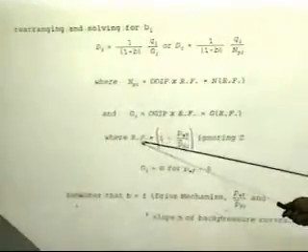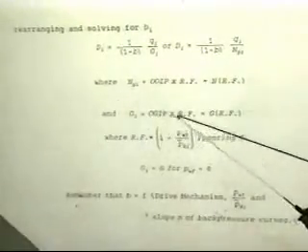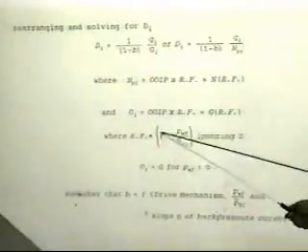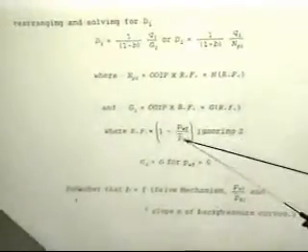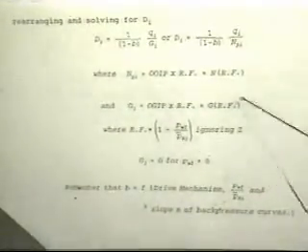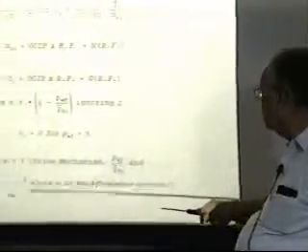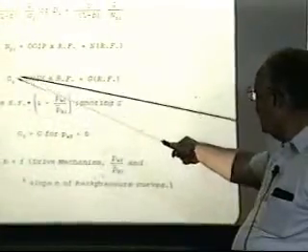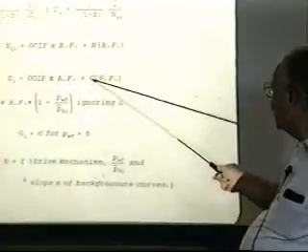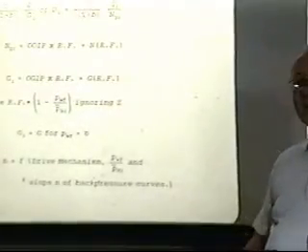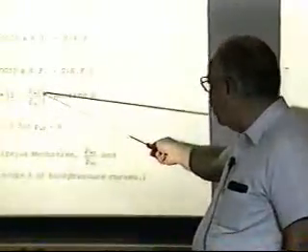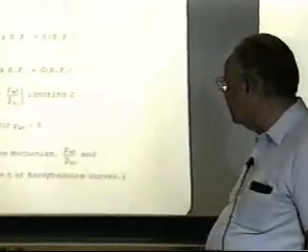The G in the equation would be the original gas in place times the recovery factor, where you define it in terms of 1 minus the flowing pressure over the shut-in pressure, if you're going to ignore Z. You can throw Z in there, but then the G sub I is equal to G. The original gas in place times the recovery factor is going to be G. So if you do the matching, you back calculate a G, you know the P sub F, you can get the original gas in place.